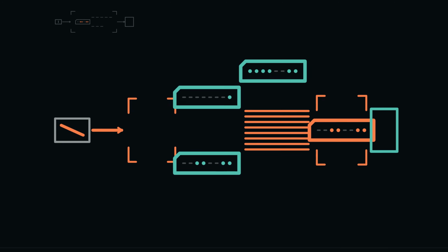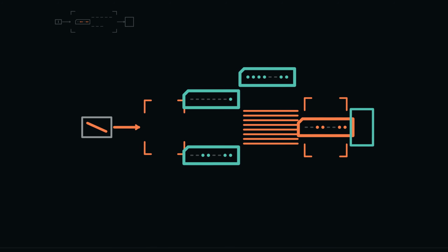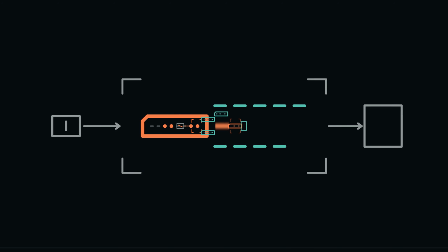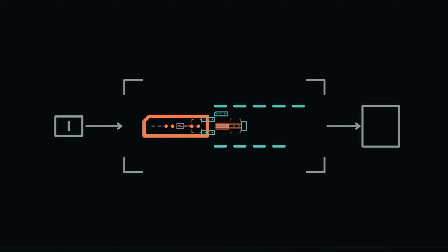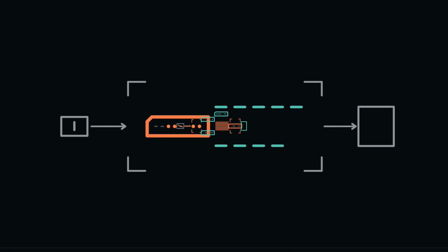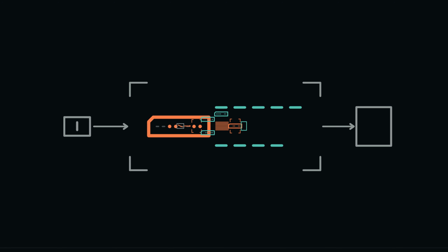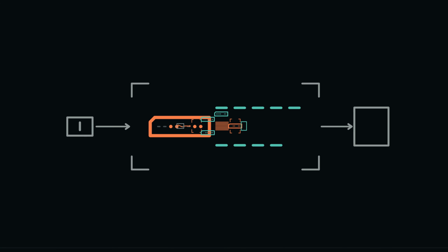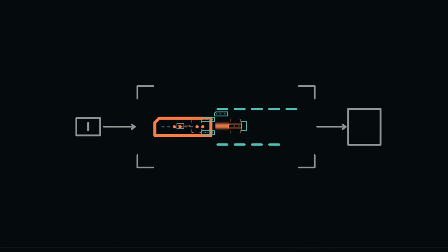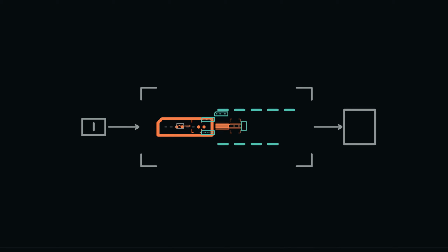The processor can now touch the world without pretending that a wire carries meaning by itself. A physical event is measured and reported. An adapter applies an interface rule. A device register exposes a byte or accepts one. The address decoder selects that register. An ordinary instruction performs the transfer. At every boundary, ask 2 questions: what physical or stored state exists here, and which rule interprets it. The next boundary begins with hexadecimal 38 in the display register. How can that code select the exact pattern of light we call the Glyph 8?